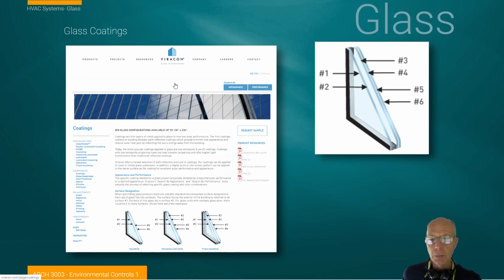In many cases, the appearance of the glass is really critical because it's one of the few controls that architects have when we start using large expanses of glass to differentiate our panels from the next building next to it. And so the color rendition, the way it reflects, how much it reflects, are all important issues. And where we choose to put coating systems on this glass radically affects the appearance of the glass.